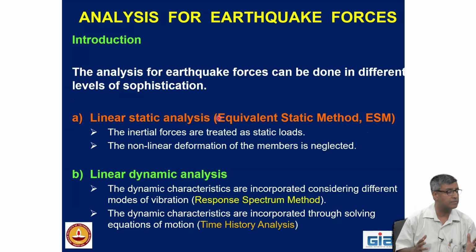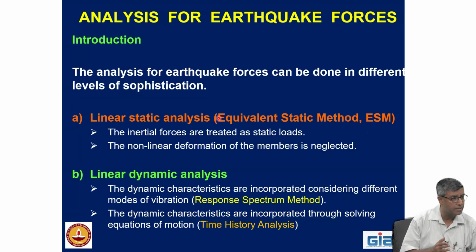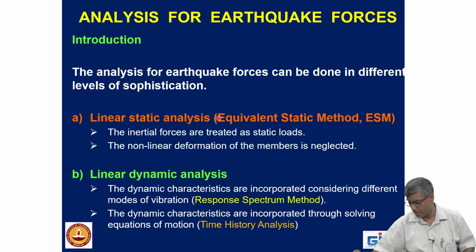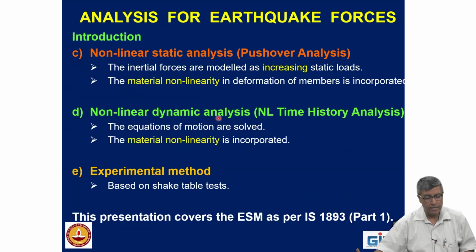What are the dynamic properties? First, you have to calculate the time periods, and for each time period, what is the mode shape. There can be a nonlinear static analysis where you are considering the nonlinear behavior of the material under a certain level of earthquake, which is called the pushover analysis. And then there can be a nonlinear dynamic analysis, which is equivalent to time history analysis, but now you are considering the nonlinear behavior of the materials. Besides this, there can be an experimental method to estimate very unique types of structures which we cannot get confidence in based on computation alone.